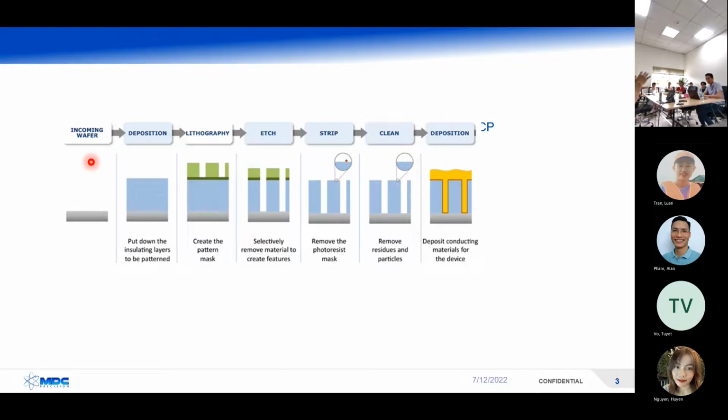In the Lam tool, we will flow gases into our gas lines. We will flow in fluorinated gases, like carbon tetrafluoride, 1 carbon and 4 fluorines, or dicarbon hexafluoride, which is 2 carbons and 6 fluorines, or sulfur hexafluoride, which is 1 sulfur atom and 6 fluorines, okay? So we will flow those kinds of gases in. For right now, think of the wafer sitting in this chamber and these gases are all around it. Then what the Lam tool does is it puts electric energy into that gas, and you get a plasma. If you remember neon lights, right now we have the yellow. If you remember a neon light, that's actually the gas neon.